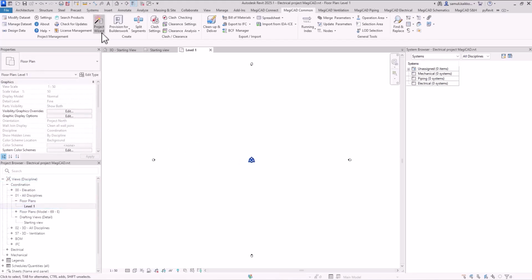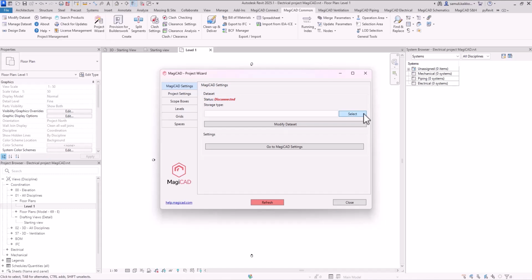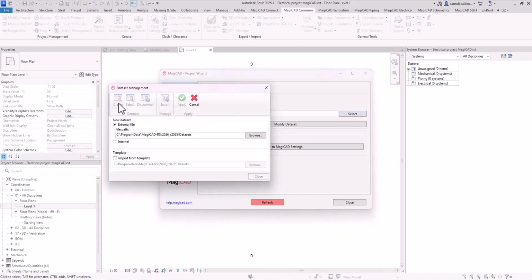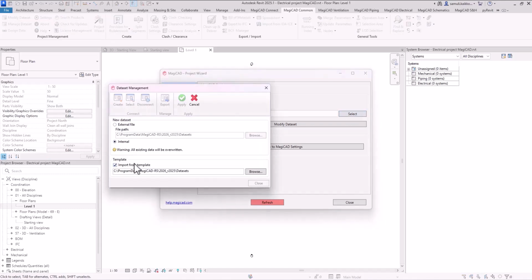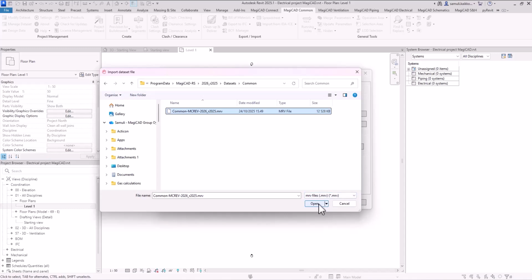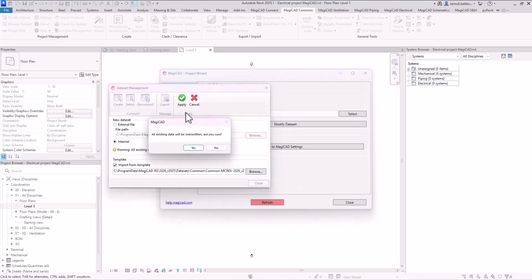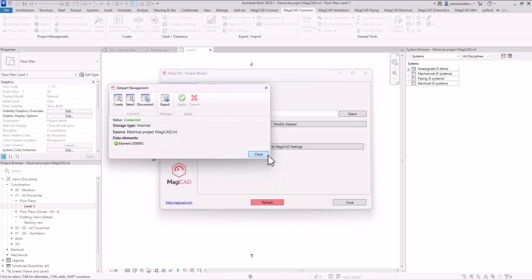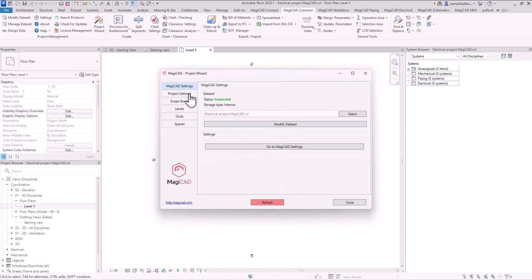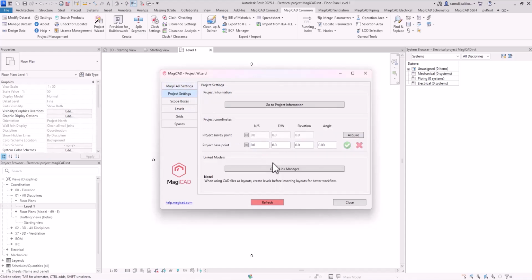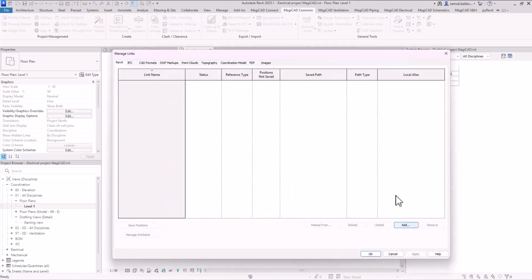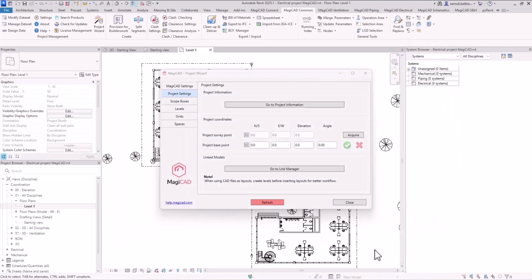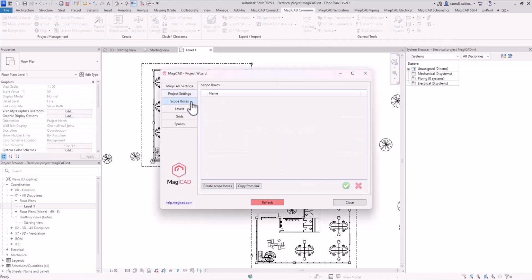In Revit, you can set up a project various ways, and most likely you need to navigate to different places. MagiCAD provides one place for all solution where you can set up all necessary settings for the project. One thing you need on behalf of Revit settings is MagiCAD dataset. That's the file where all MagiCAD related data is collected and finally imported to Revit project.